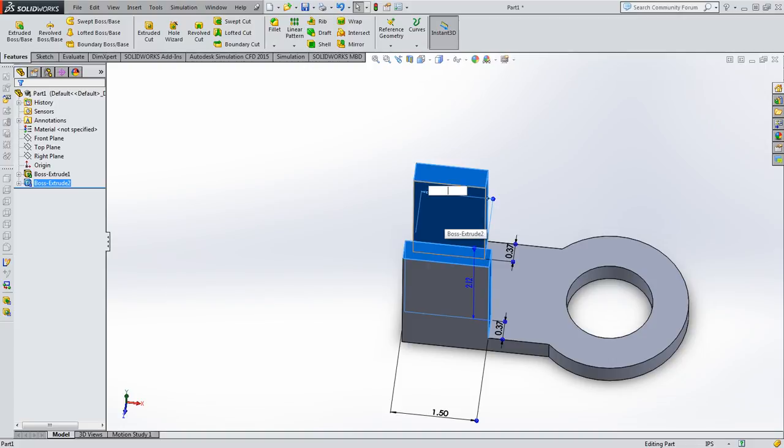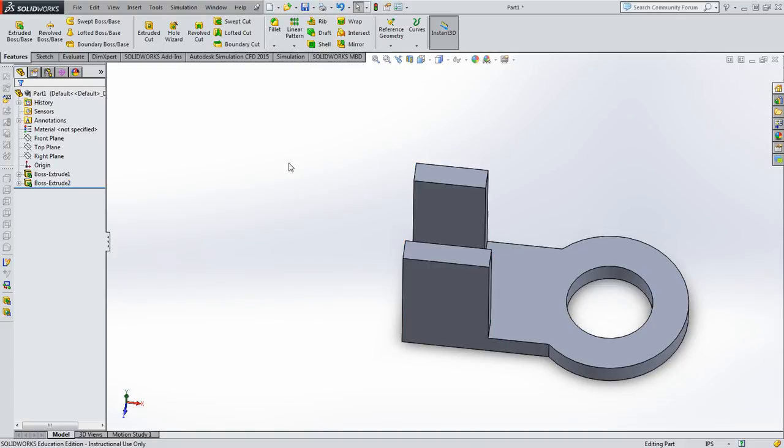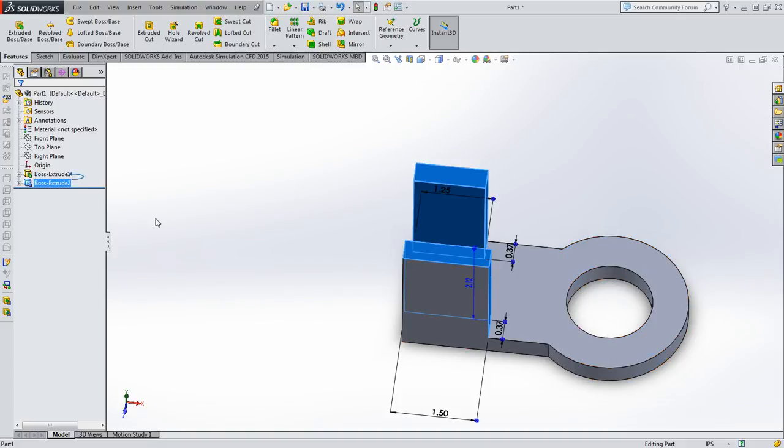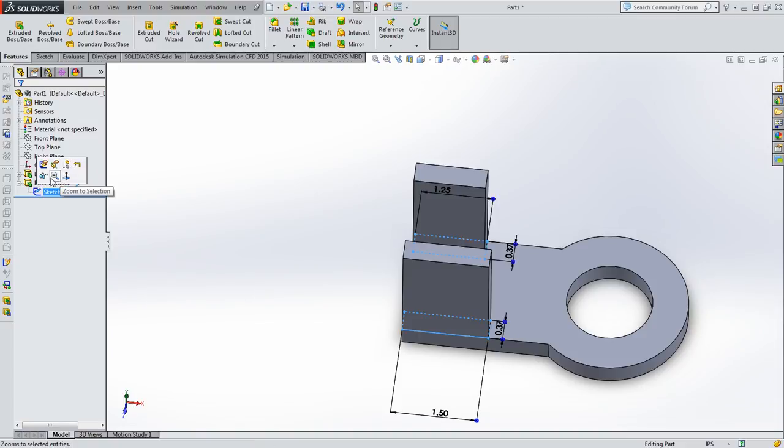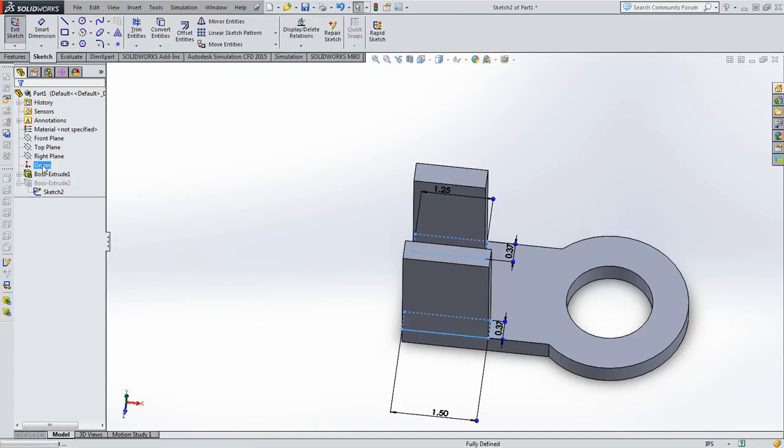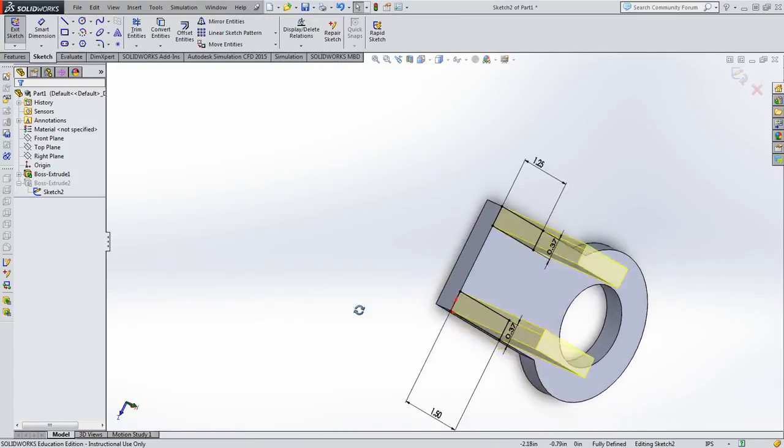1.5. Press enter, it will fix your problem. If it doesn't, click the traffic light and it'll update. I'm going to go into the sketch just so you know sometimes when you click these, the numbers don't show up. So we're going to open up the 3D feature that made that. We're going to click on the 2D sketch that's inside, and when you click it, notice the box of other options that appear. Top left choice will let you edit. Now you're back in the sketch.